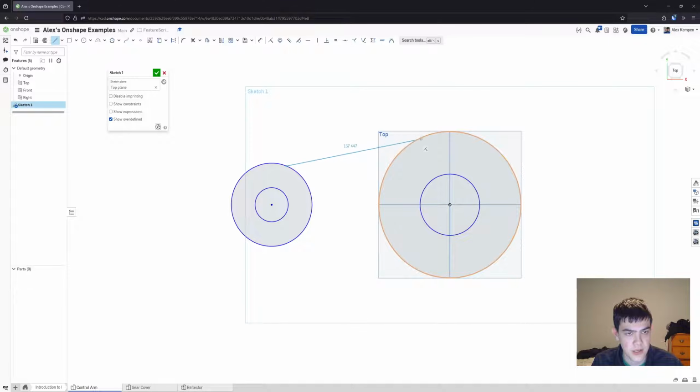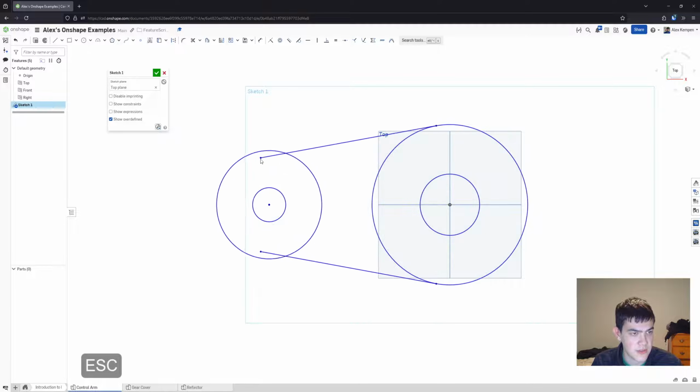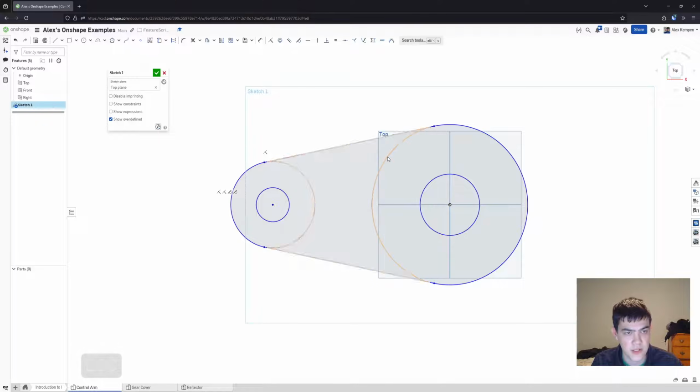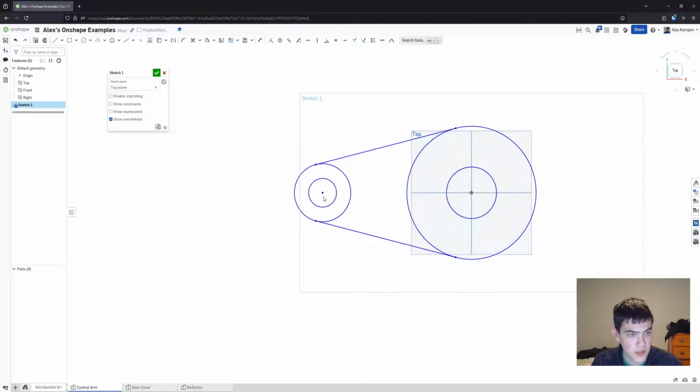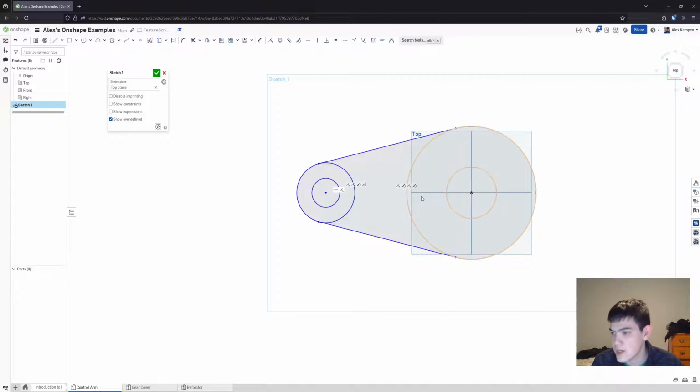Here I can see I can get a coincident. I can also get a tangent, which is what I do eventually want. So I can grab that, repeat down here as well, and then I'll add my missing tangent constraint here and here. Now we can see these create a smooth connection, and it touches thanks to the coincident. Yeah, so that's good. This is horizontally inline, which we like as well.